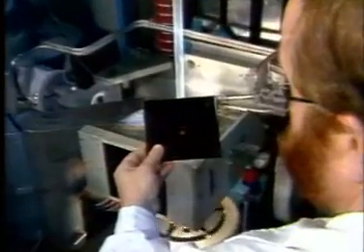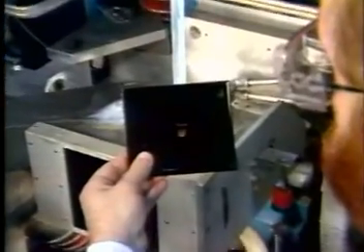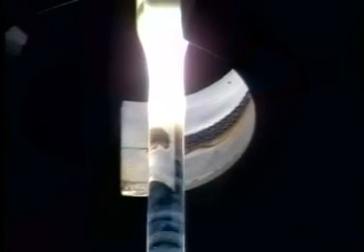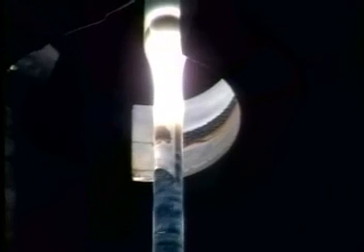These layers will form the fiber's core, while the tube becomes the cladding. When enough core material has been built up, the tube is strongly heated to collapse it into a solid rod called a preform, which is a scale model of the finished fiber, only much shorter and thicker. The preform is then installed in a drawing tower, where it is melted and stretched into an optical fiber many kilometers in length.